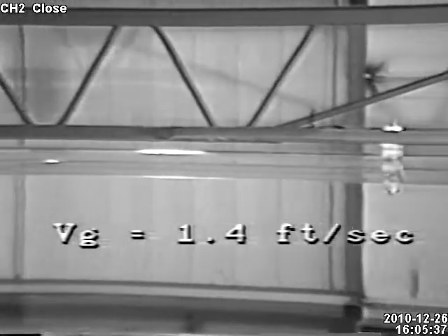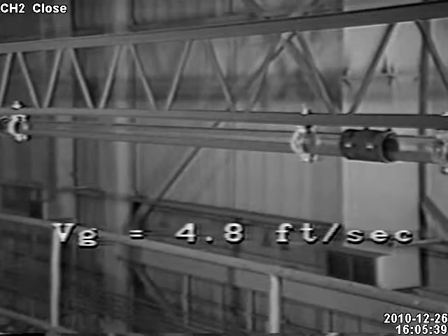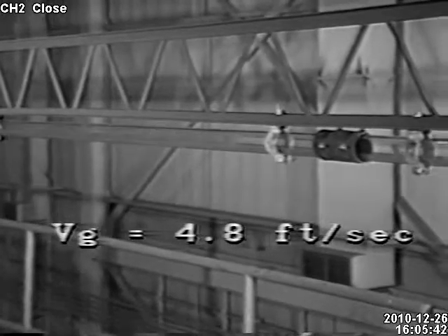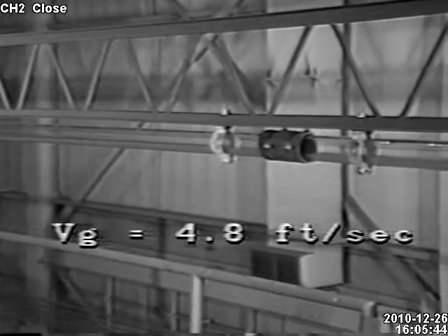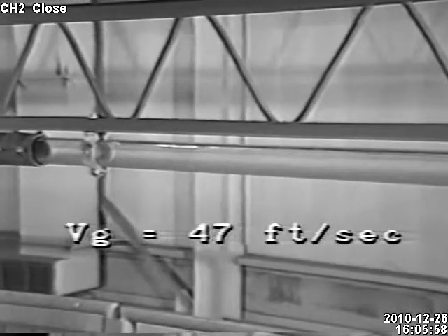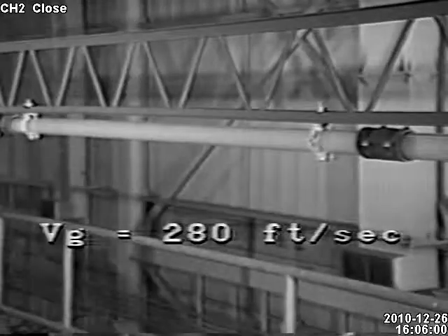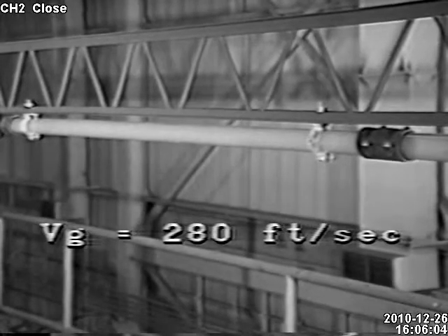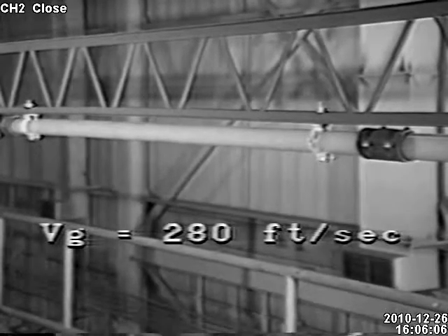At the lowest velocity, the surface is fairly smooth with small waves coming by. A bubbly plug flow occurs at a slightly higher speed. At this condition, the surface is choppy or rippled. Under these conditions, a cresting annular flow condition exists. And at this speed, most of the liquid is being transported as droplets with some liquid film at the wall.